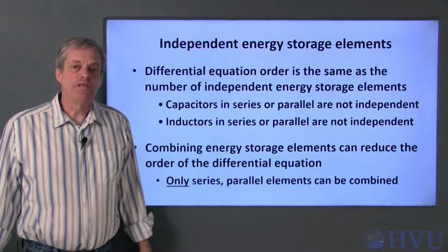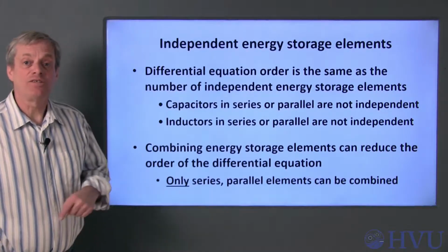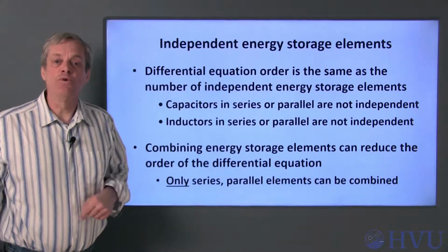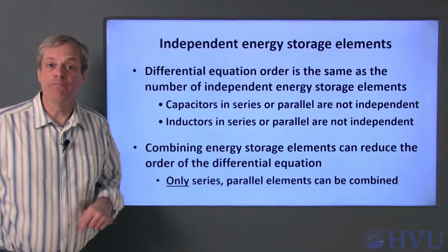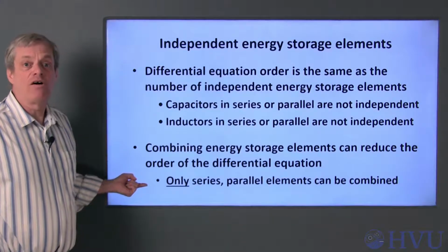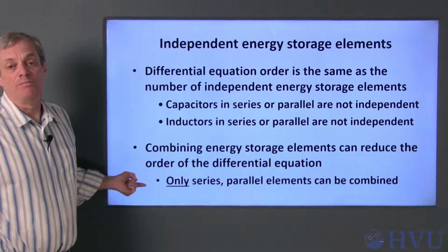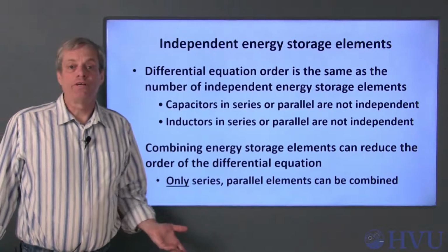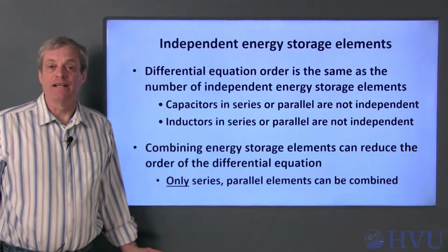The benefit in doing this is significant, but as with resistors, be sure that you don't combine elements that shouldn't be combined. Make sure that the energy storage elements you're combining are in either series or parallel before combining them. No other configurations allow you to combine elements.